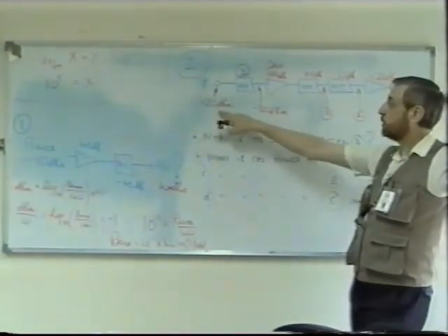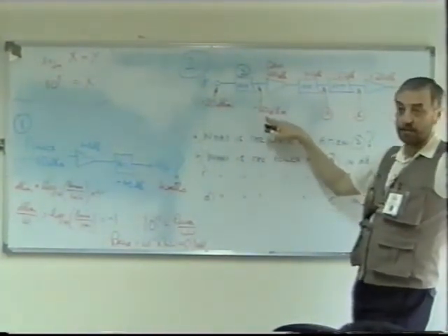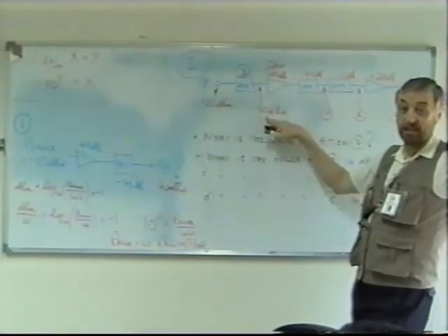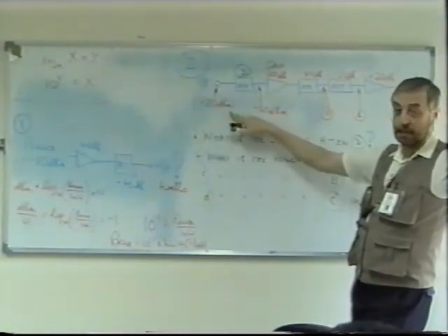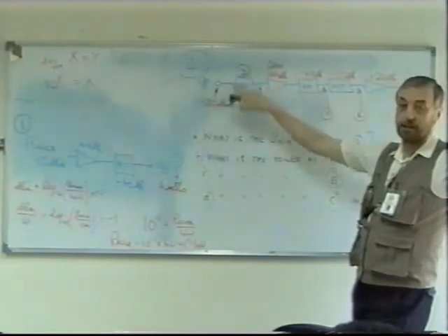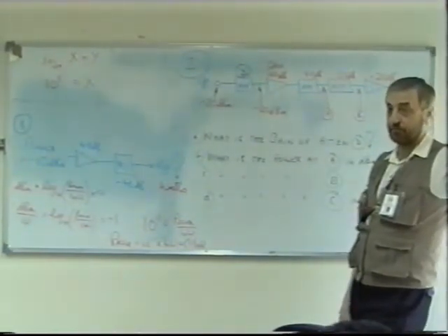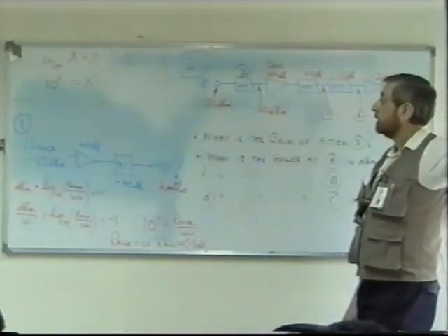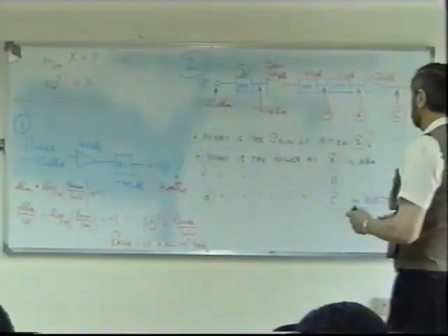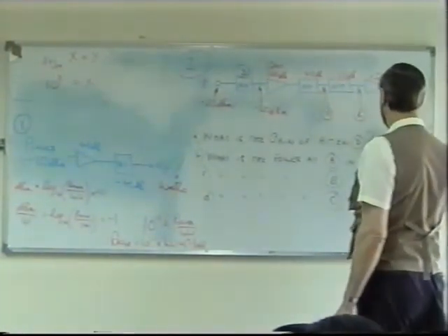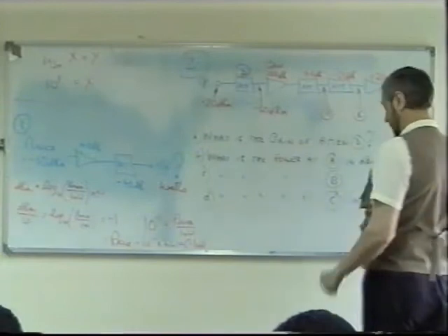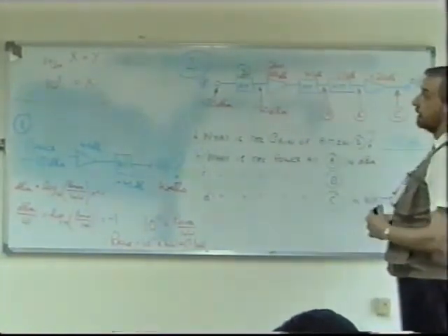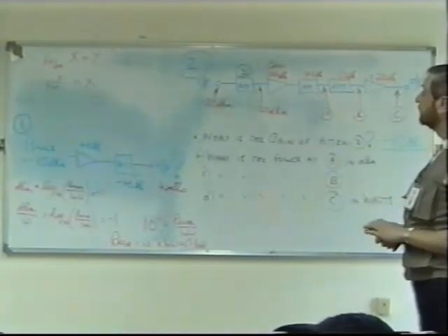We begin with minus 20 dBm, and here we have minus 30 dBm, so it must be minus 10, mustn't it? It's a straight addition. Minus 20 plus minus 10 is minus 30, so this must be minus 10. There's not much calculation involved in that question. So the answer to A is minus 10 dBs. In other words, the ratio between output and input expressed in dBs is minus 10.